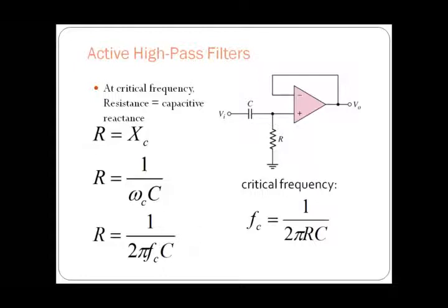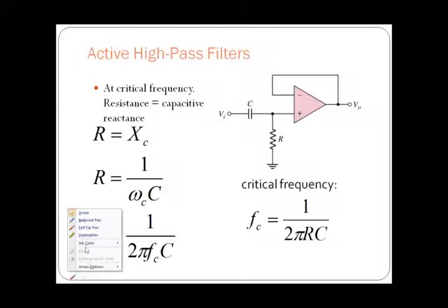Here, high pass filter indicates that we are going to give the input signal directly to the capacitor, and we are going to take the output from a resistor, and that output will be provided as an input to the operational amplifier. Here we have considered the op amp as a non-inverting amplifier. That is, we have given the input signal through a high pass RC circuit to the non-inverting terminal of the op amp, whereas the inverting terminal of the op amp is used as feedback.